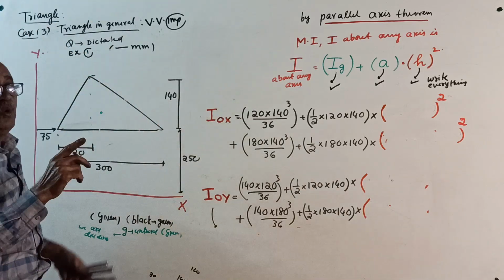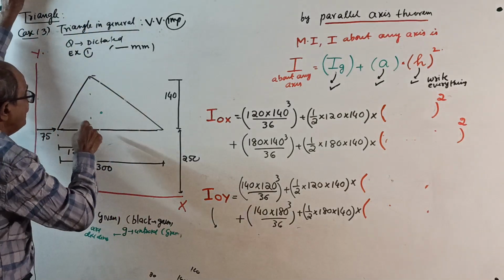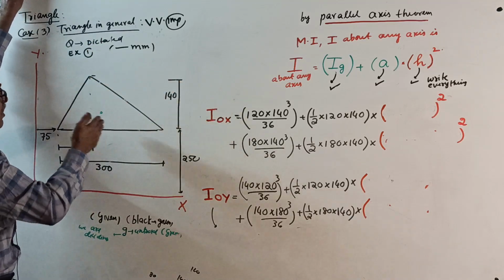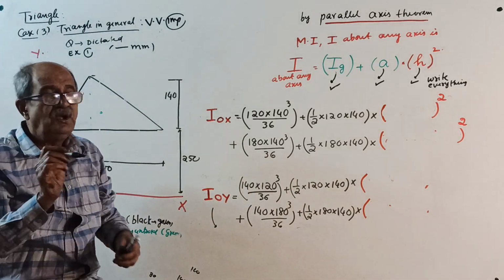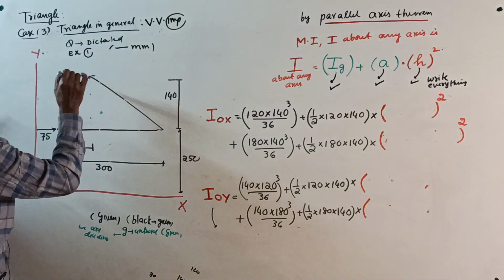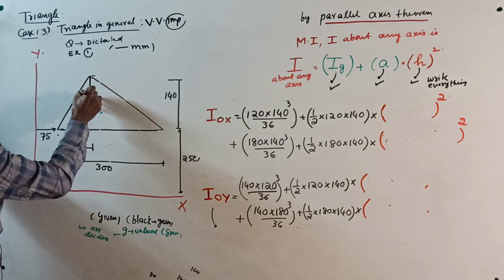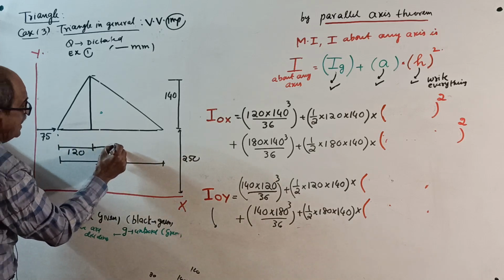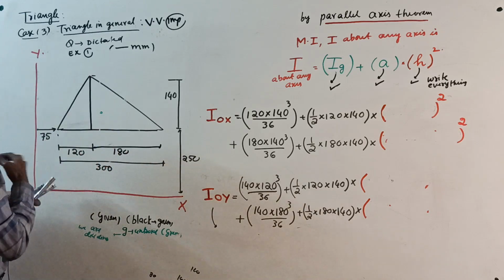There is no standard expression for moment of inertia for the axis passing through the centroid and perpendicular to the base, because it is shifted. You write the statement and then write, therefore, the best option is to draw one more sketch. If you are lazy and do not do it, you are losing. Write one more sketch. If this is 120, you calculate this one, it is 180.